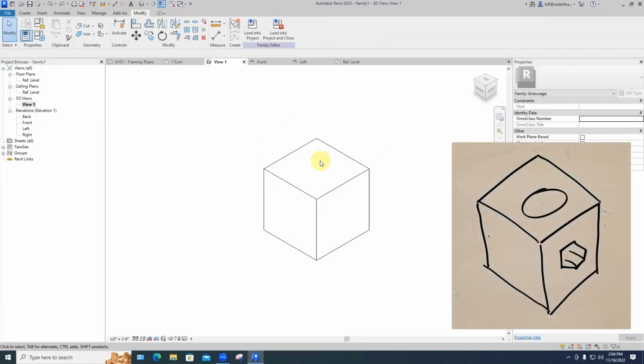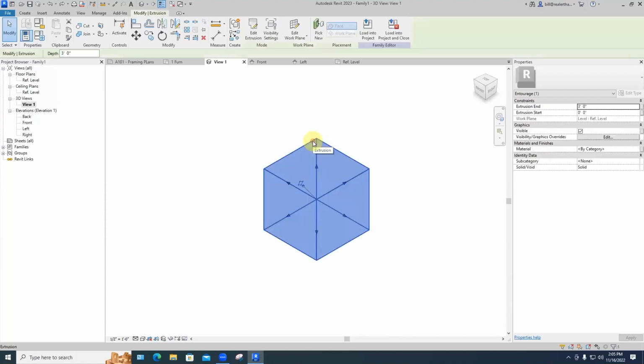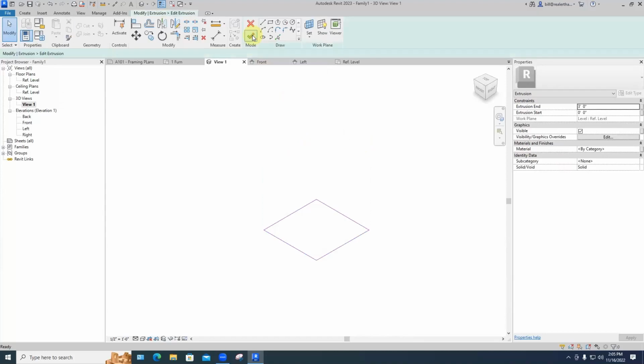So how do we drill a vertical hole, let's say 2 vertical holes through that? The question is, based on the tools we used last class, what are at least 2 ways we could drill some vertical holes through here? Anytime that we've created those magenta boundary outlines, whether it's for a horizontal object or the profile of a wall, we can select the object, go back to Edit Extrusion, and if you remember, then anything that we draw inside here will become a void hole through it. So I'm going to create maybe a couple of circular holes.